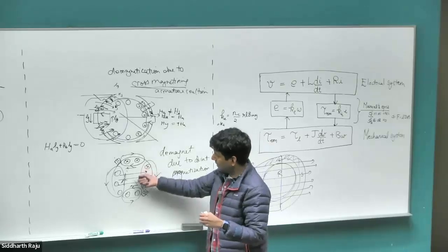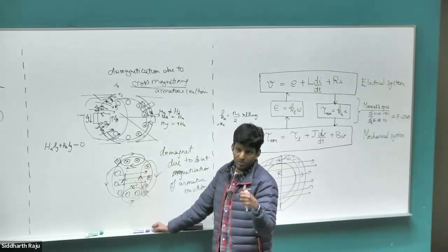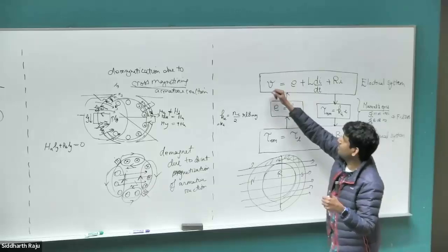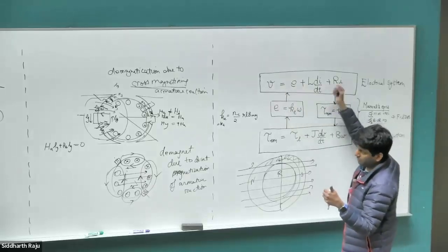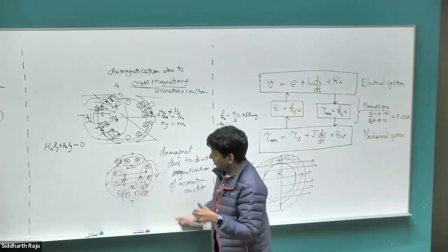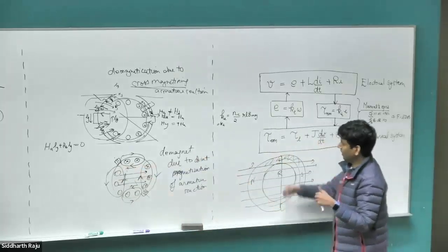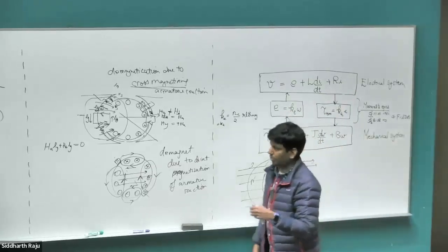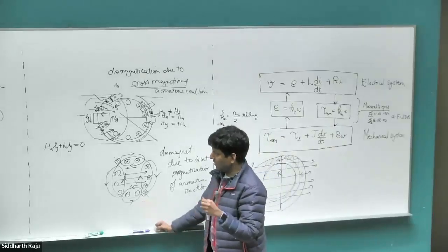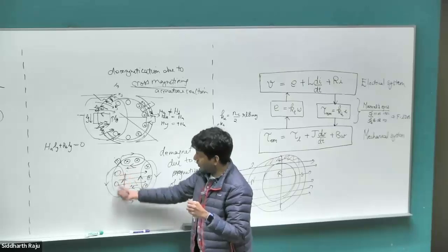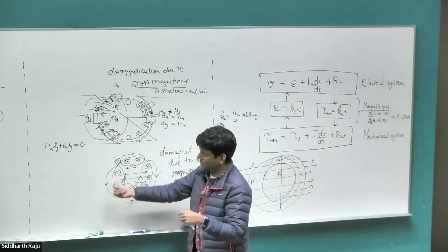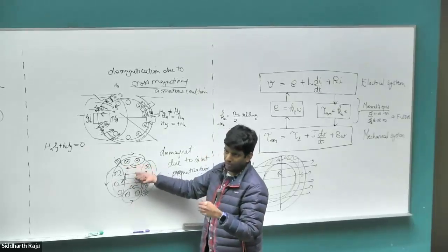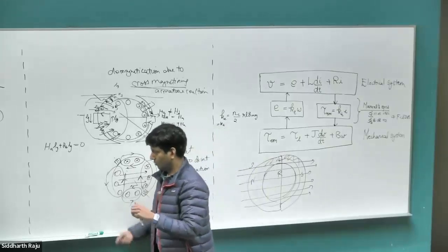Because as the load increases, the speed of the system would come down, EMF comes down, the current increases, right? If the EMF reduces, V minus E increases, that means the current increases. If the current increases, there is more demagnetizing field, which will then reduce the torque even further. And then as the torque reduces, the speed reduces, the EMF reduces, the current increases. It's an infinite cycle to the point where the motor will come to a stop. This usually happens when the core is saturated, and no matter how much more current you push in, the magnetic field is not increasing. So there is no additional torque produced, but this is constantly demagnetizing it as more and more current increases. So the torque starts to reduce and it comes to a full stop.